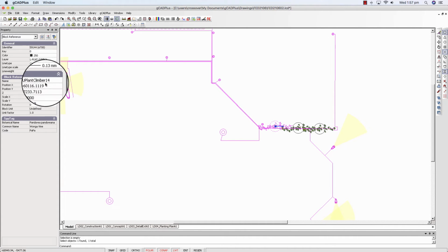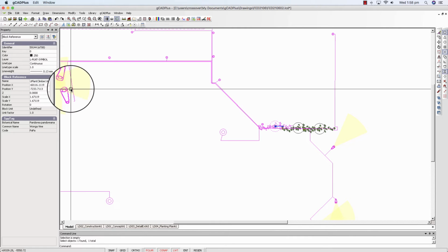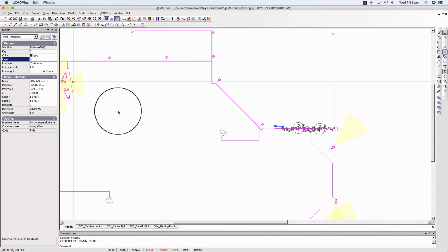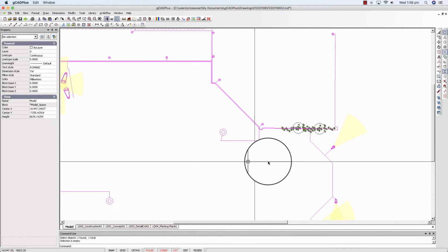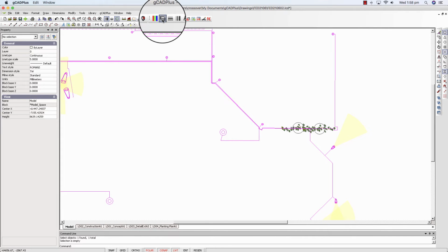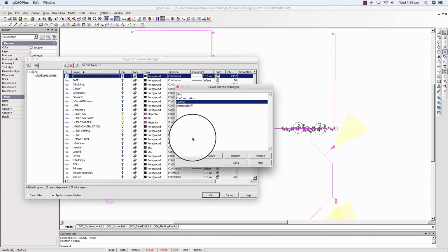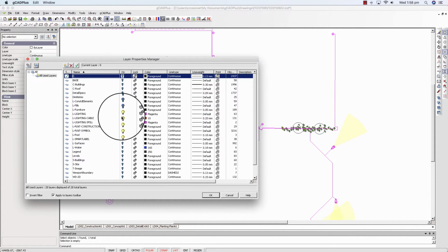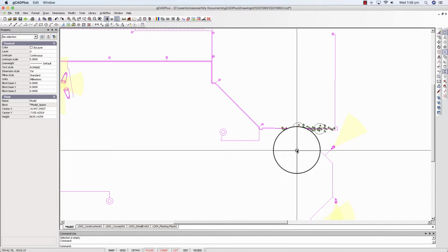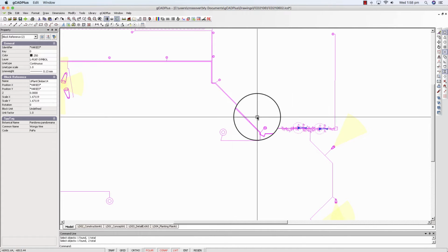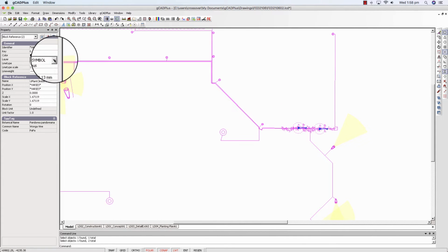It's a symbol called U-Plant Climber, but it's been put on a layer called L symbol, and we really need to put that back on layer 0, and it disappears because with this particular lighting layer state, we've got layer 0 turned off. Even though it's still current, it's turned off. So clearly these 3 symbols here were just inadvertently put on the wrong layer.